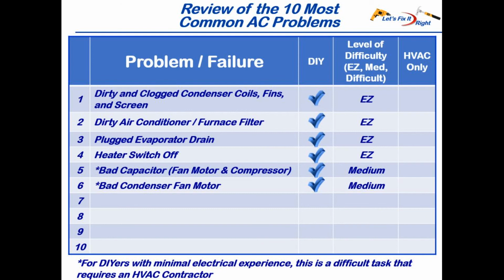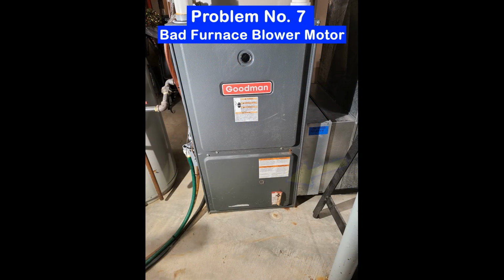For the unexperienced electrical folks, it's a difficult task that requires an HVAC contractor. If your furnace squirrel cage blower motor in the lower compartment of your heater makes noise or will not run, it could be the blower motor or the blower motor's capacitor.